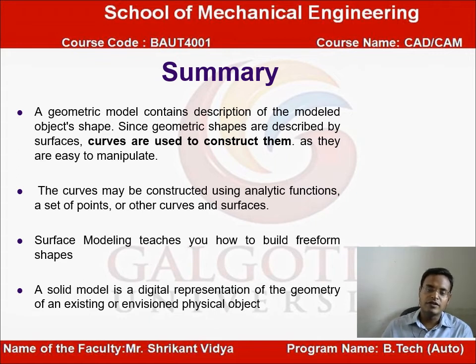So whatever we discussed among wireframe modeling, surface modeling, and solid modeling, solid modeling is generally suitable for modeling because it is a sort of digital representation. It shows how an object looks from the interior as well as the exterior point of view. So we can do all the calculations, stress analysis, structure analysis, and information analysis; all the analysis can be done on the solid model. That's why solid modeling is used on a larger scale and in common life. But in wireframe modeling, we show only the corners and edges, so we cannot do load analysis of the whole part and so on. So solid modeling is generally used on the larger scale.